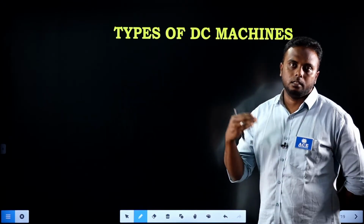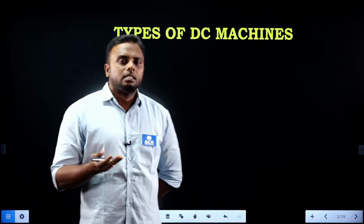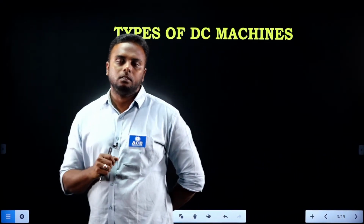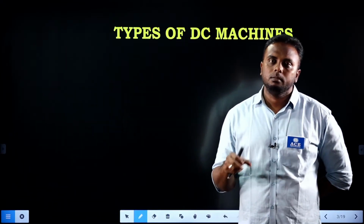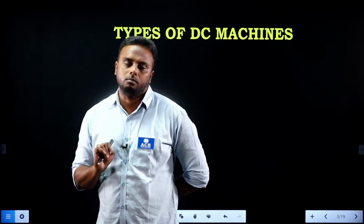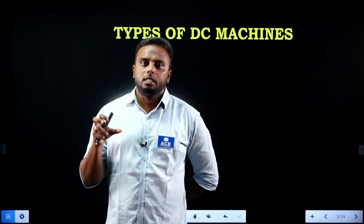Cumulative we can get in three different models, that is over compound, flat compound and under compound DC machines. Based on the type of connection, how we connected the field windings, we have two more types: short shunt and long shunt, that is, long shunt compound machine and short shunt compound machine. So mainly two types only, cumulative and differential. Again cumulative has three types: over compound, flat compound, under compound. Briefly, I will give some information regarding how to get these three types of cumulative compound machine.